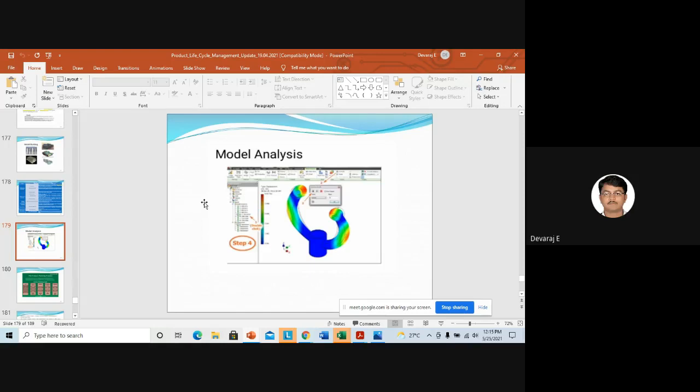Yes, that is called modal vibrations. Modal analysis is nothing but finding the frequencies of the structure. If you take buildings, the building can fail due to the first frequency or second frequency. When the external excitation is equal to the natural frequency, then resonance comes into picture, right? I told you this in mechanical vibration. So modal analysis is nothing but finding the frequencies of the structure.